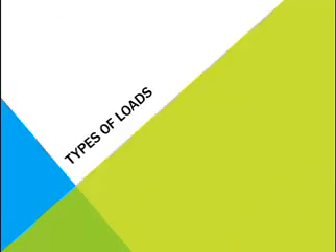Establishment of the loads that act on a structure is one of the very important steps in the design of a structure. Once the primary form of the structure is determined, that means once the preliminary dimension is finalized and type of members are selected, the actual design begins with those elements that are subjected to the primary loads the structure is intended to carry and proceeds in sequence to the various load supporting members until the foundation is reached.